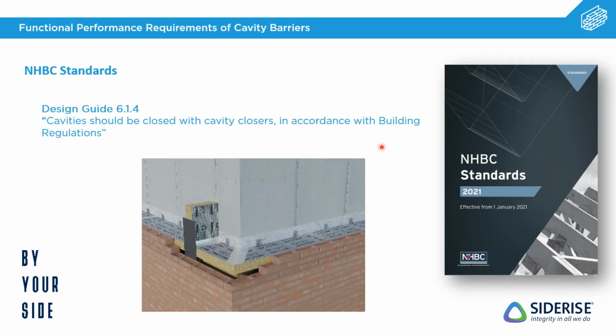As mentioned before, there's also some other guidance out there. A very common one that you'll see is the design guide from the NHBC being utilised. And with masonry, they actually very much follow suit in terms of what cavity barrier locations the regulations require. It does interestingly have an increased requirement when you're looking at cladding or ventilated facades.